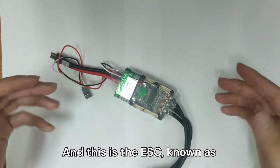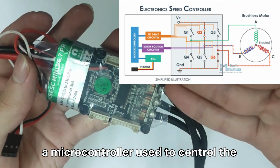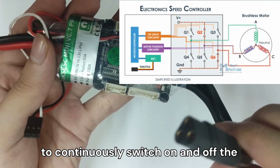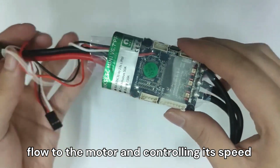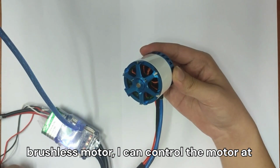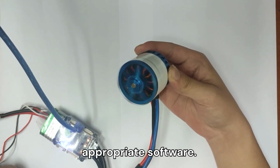And this is the ESC, known as the electronic speed controller. It is a microcontroller used to control the brushless motor. It uses MOSFETs to continuously switch on and off the terminals, thereby regulating the current flow to the motor and controlling its speed and direction. By connecting the ESC to my laptop and the brushless motor, I can control the motor at any desired speed with the help of appropriate software.